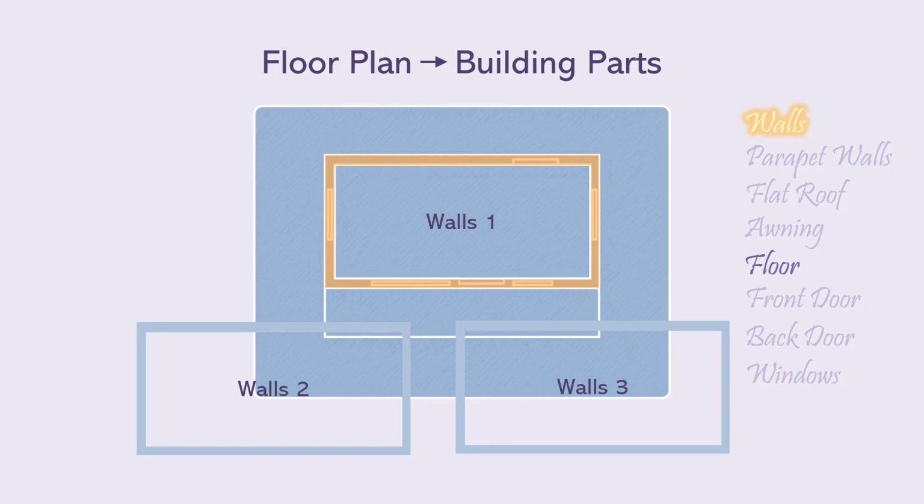We'll remove parts of the bottom wall to create the doors. Draw rectangles that match the widths of the doors in the design. Duplicate and align these door cutout shapes. Use one set for the door cutouts for this bottom wall shape. We'll use the second set for the door cutouts for the middle wall.